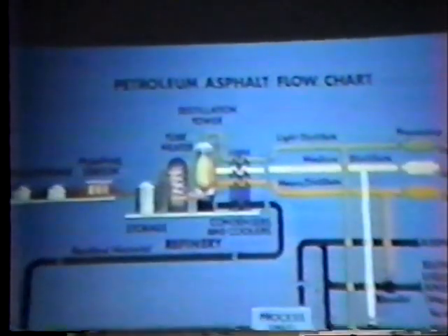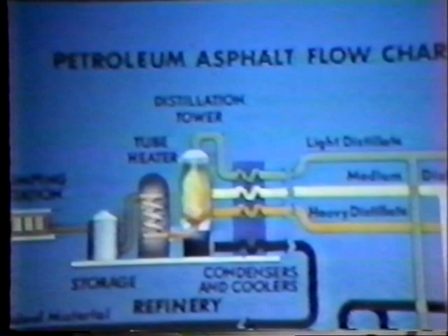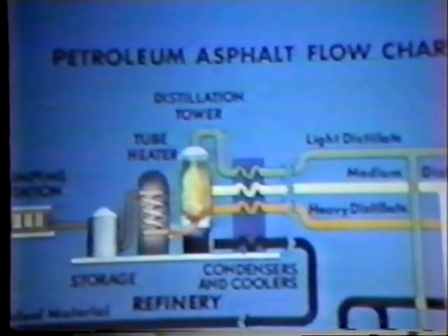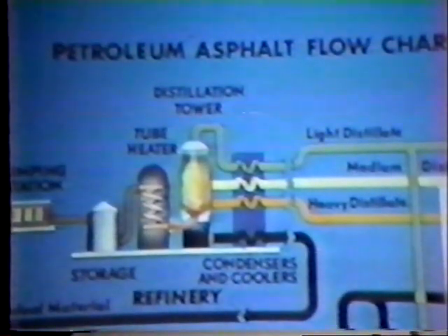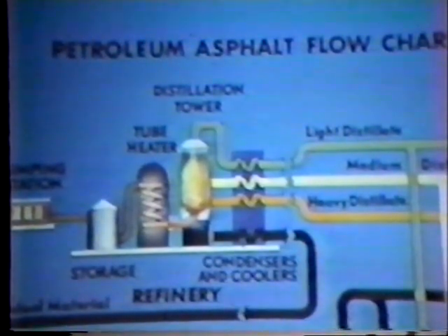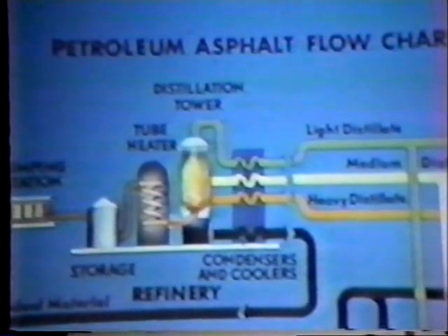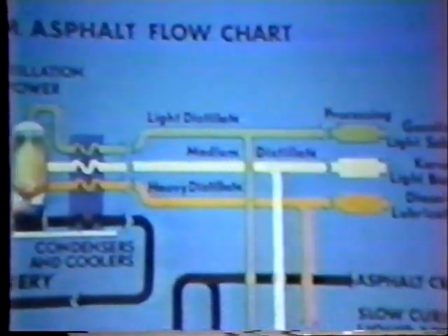As the charts show, all asphalt that we use for road paving today comes from crude petroleum. It comes out of the ground. As you can see, it's brought to the refinery tower where heat that runs all the way from 1,000 degrees at the bottom up to about 350 near the top apply different temperatures to the product, and by that process, different products of different volatility are gathered off.